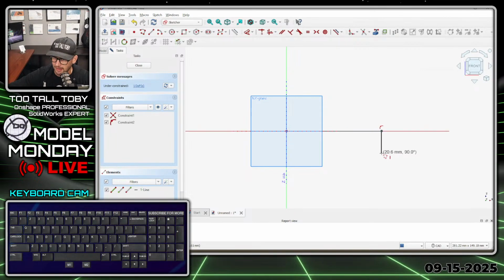Come straight down here like so, maybe 18 millimeters down, or maybe it's actually a little less, 13 millimeters down here. I'm just using the on-screen feedback, making sure that these entities are approximately the correct length, and that I'm getting my horizontal and vertical relationships as I'm sketching this geometry. And now this one's going to come over here, coming up at an angle.